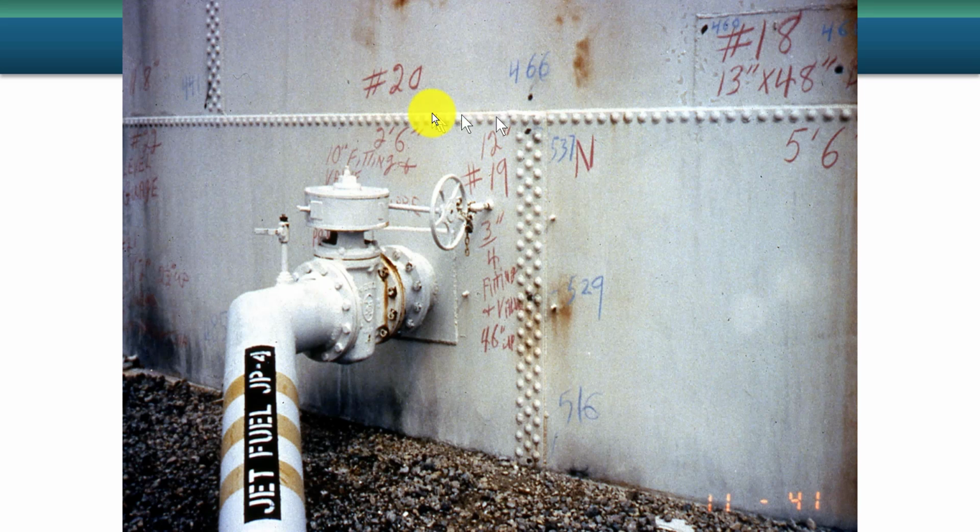They have their issues, no doubt. Sometimes there's a leak, or if you try to repair them, you can end up with the expansion from welding the head of one rivet just propagating, and you'd end up having to weld all the rivets in a tank. So it's a gamble as to whether or not you can repair a riveted tank. It's truly a gamble. But often it works. I would say more often than not, and it's well worth the money saved. I'll just point out that this dirt on top of the chime is poor practice from a corrosion perspective, because the dirt retains the moisture and is ideal for corrosion to take place.